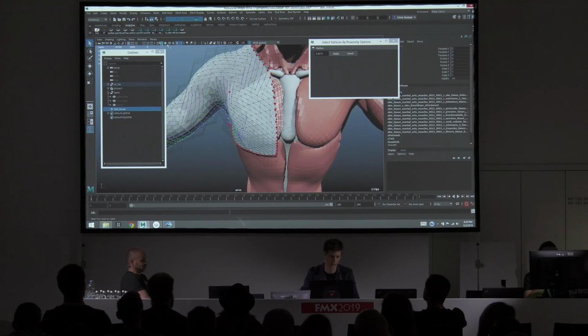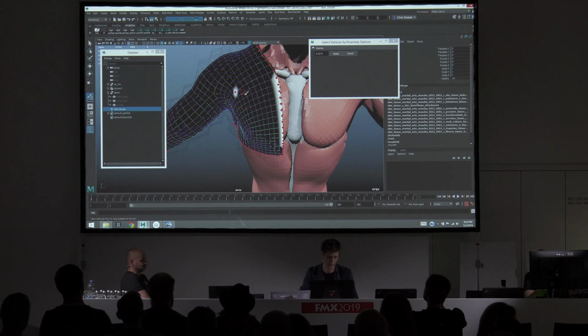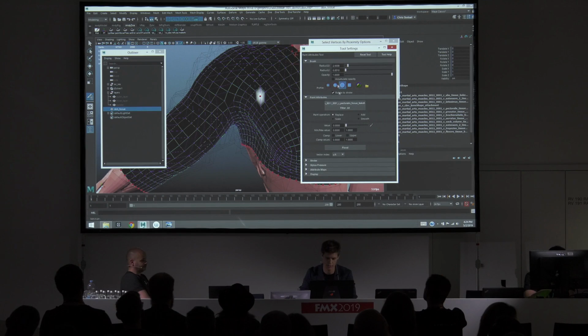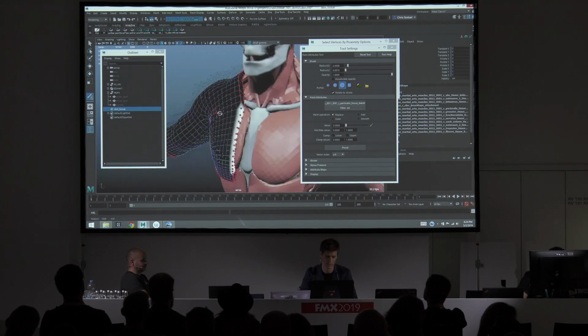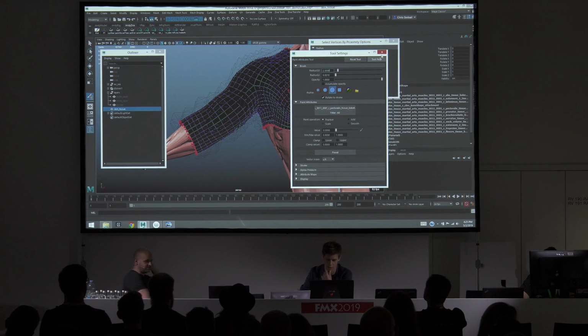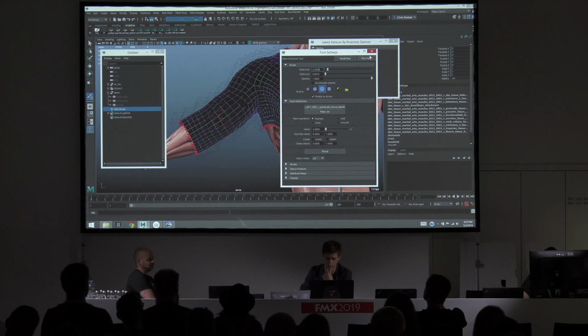So this is another thing I can show, that a lot of the maps in Ziva are paintable. If I wanted to change this attachment after I'd made it, you can see there's actually a grayscale map. I don't want that attachment on that vertex there, so I can just replace it by painting it off to 0. This is really common in Ziva. Many things are paintable like this, and you can alter them after the fact, which is quite cool. It's also the means by which we're able to transfer setups from one character to another, which we'll look at later.